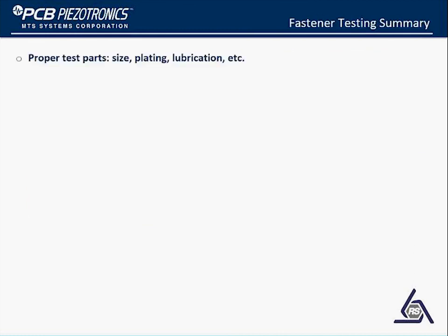So for fastener testing, what do you need to know before setting up and running a test? Well, you need to know what the specifications are for the proper test parts: the size, the plating, the state of lubrication, cleanliness. Do you have to clean them to remove all of the lubrication? Or just what are the requirements as specified by the test standard? You need to know what the temperature of your parts should be. Is it just ambient room temperature, or are there special specifications for this?